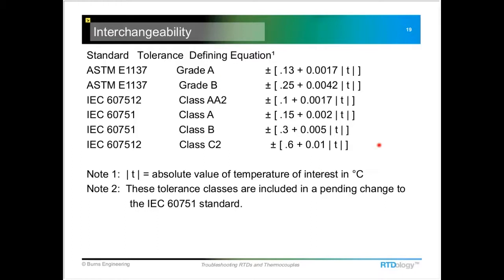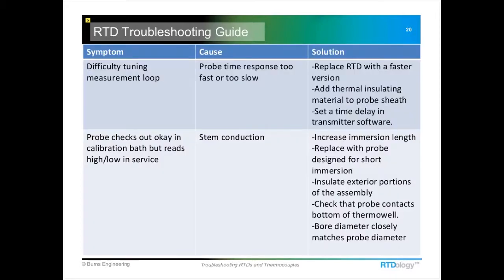So that's a real good, accurate, easy way to test the probe to see if it's working correctly, if it's been affected by vibration. And once again, I'm going to mention that before you do an ice bath test, you should do the insulation resistance test. If you have poor insulation resistance, there's a possibility you can get some non-repeatable measurements out of this ice bath test.